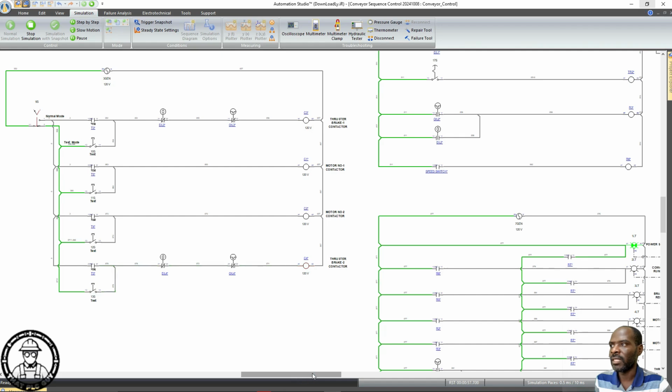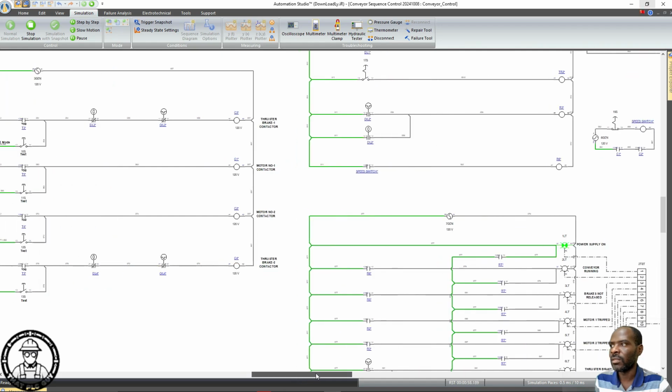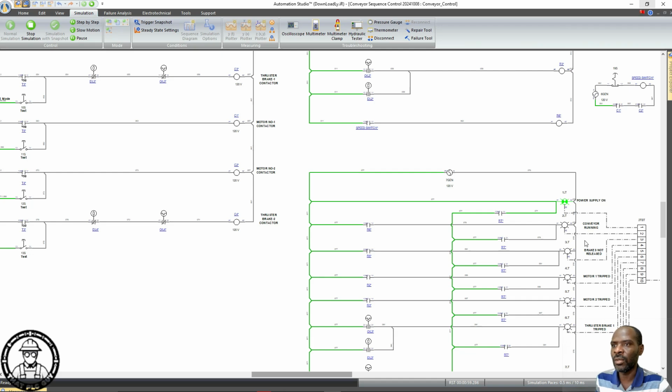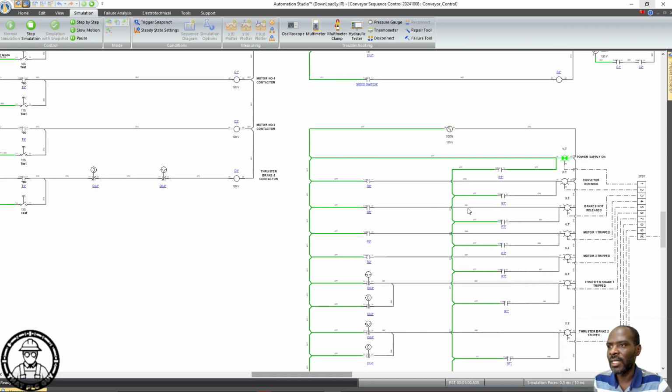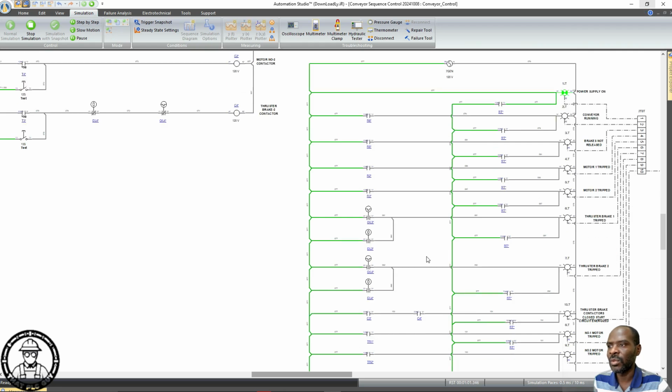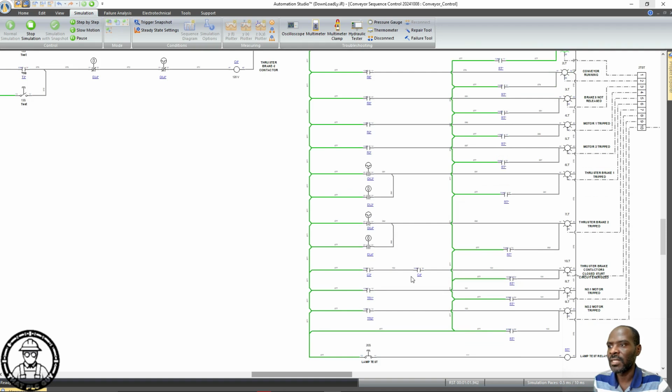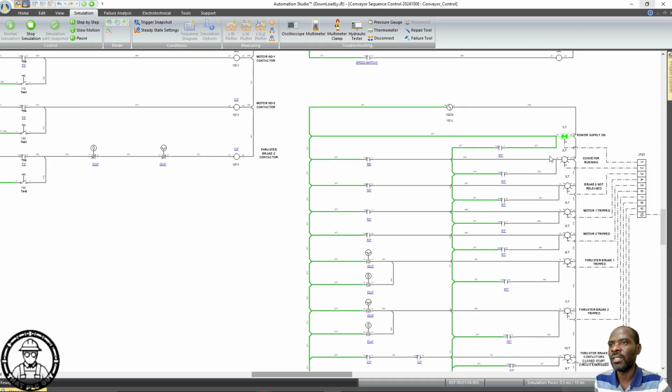But again, it might be of interest to look at this in association to the indicator lamps. Okay, so I've got R6. This can only be observed in the starting sequence, but to test the lamps again, remember we just needed to push the lamp test button. Okay, we just needed to push this right here. Then all the lamps come on, showing you that all the lamps are in good condition, and if you needed to change one of the lamps which was broken, then you can do so, but that's just about it. That does it for the lamp test.